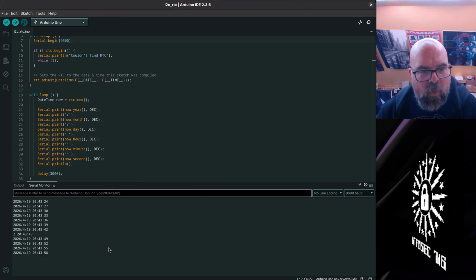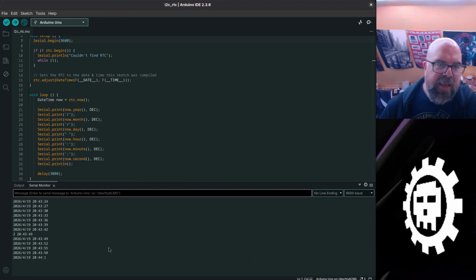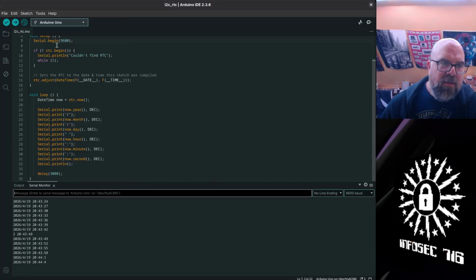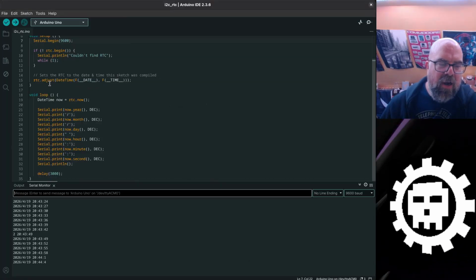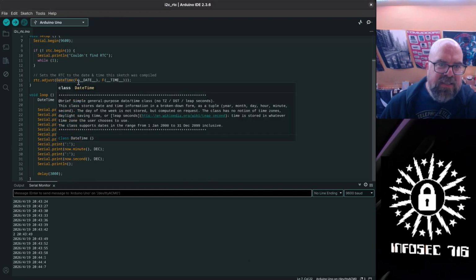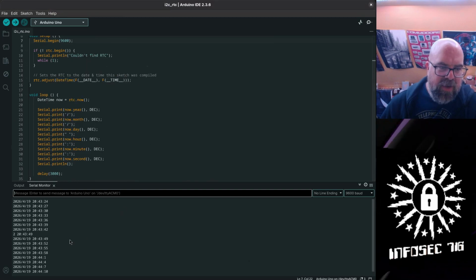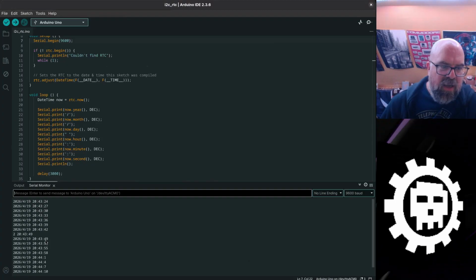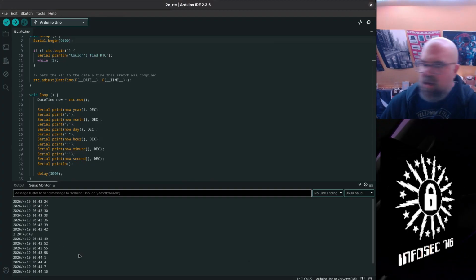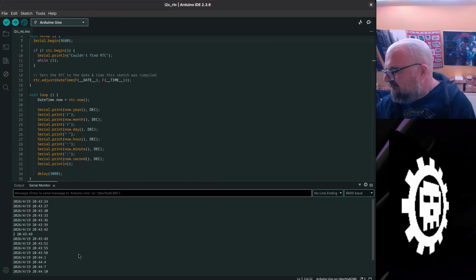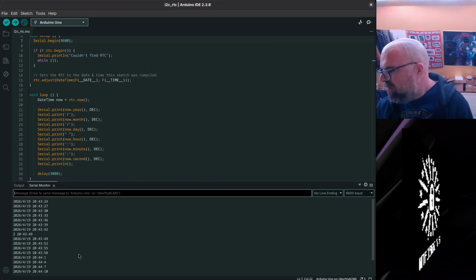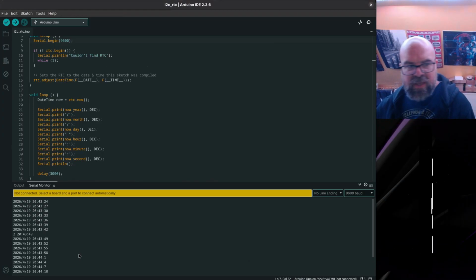Now, one weakness that I want to point out is, as you see in the setup function here, it sets it to the date and time that the sketch is compiled, not the time that it's uploaded. So this is 20:43:49. If I unplug this from the power, okay, you see not connected.